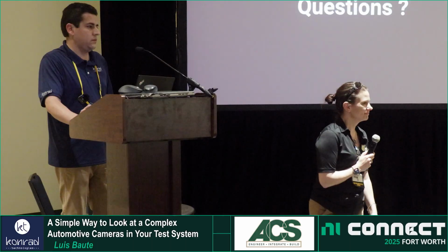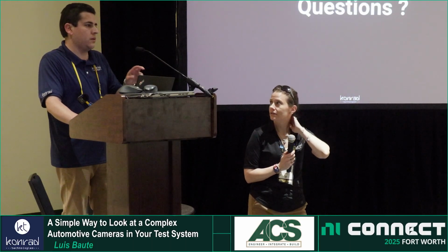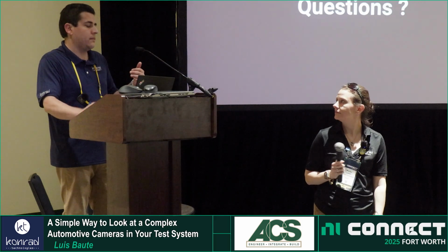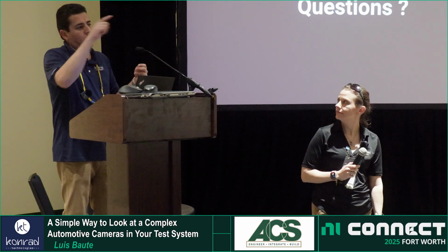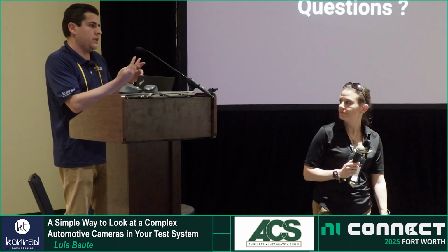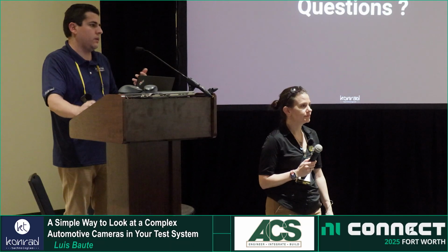There are two different CRCs. One we can fault, one we cannot, because when we were serializing it back out, it fixed it. When you look up these cameras or the cards, you can look for pixel mode and tunneling mode. The first one carries the CRC all the way, like for example in tap mode. So even though we changed it in the FPGA, it was taken from what was received at the beginning, and we were not able to.